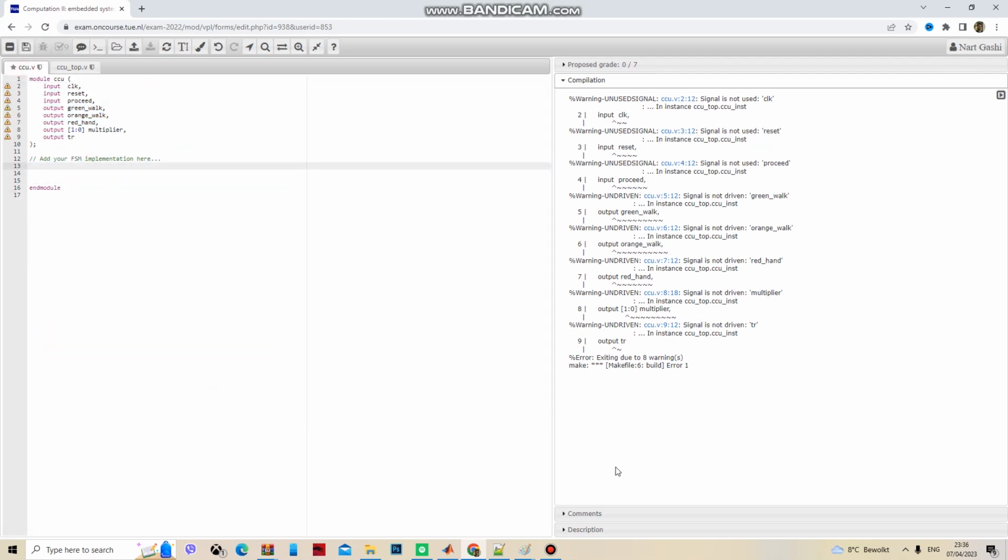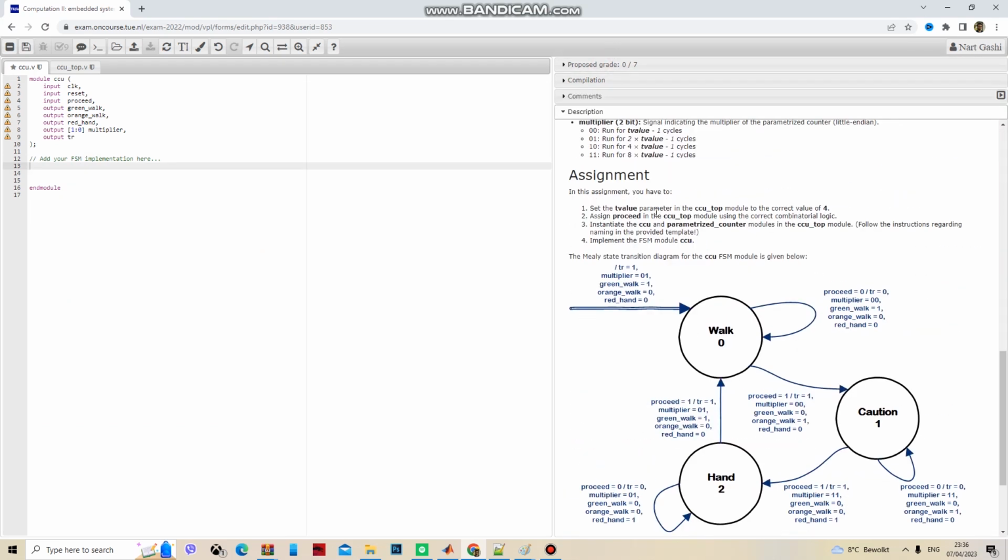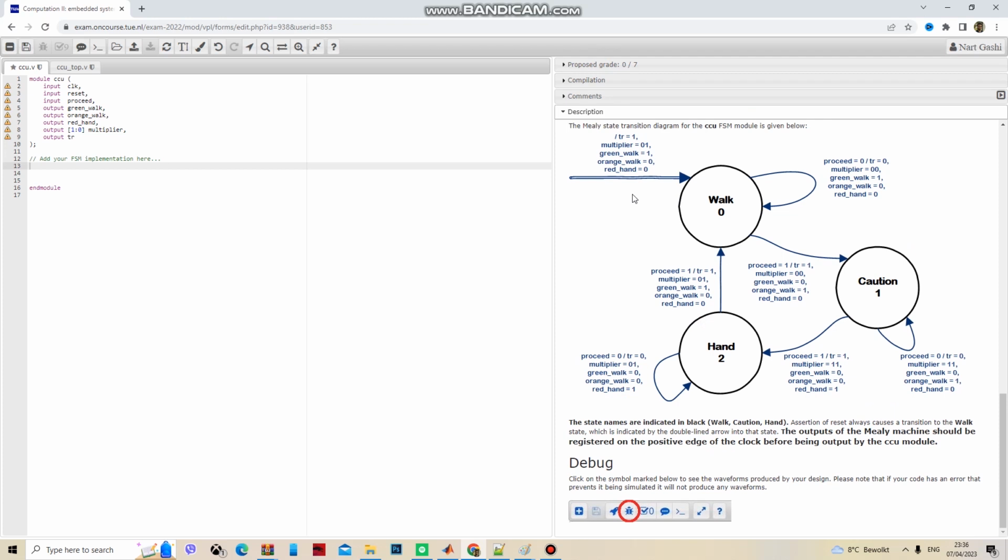This is like every other finite state machine that you've done, but unlike exercise 2D, where you would only update on every transition, here it is specified in bold that it should only update on the positive edge of the clock. So unlike in 2D, here we should keep track to only update on the positive edge of the clock, which means every register will have its sequential counterpart.